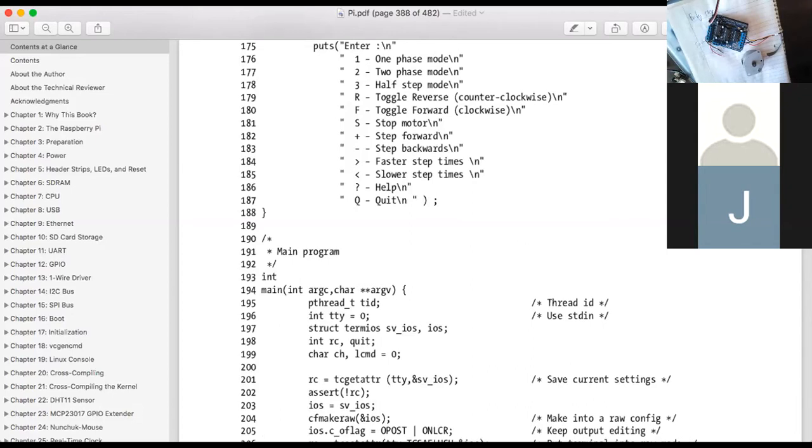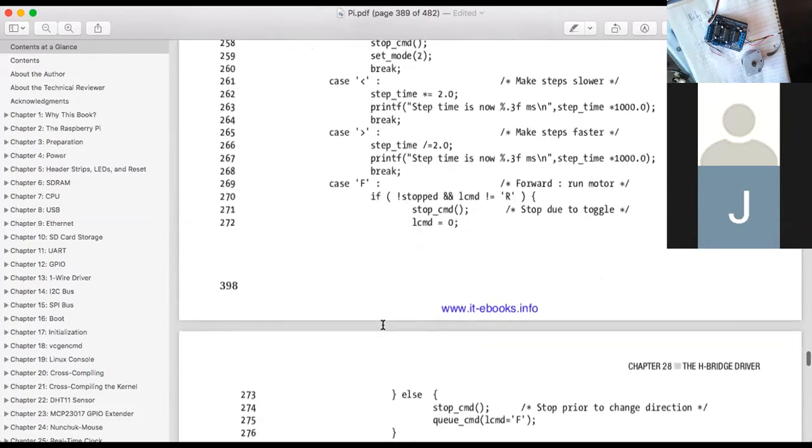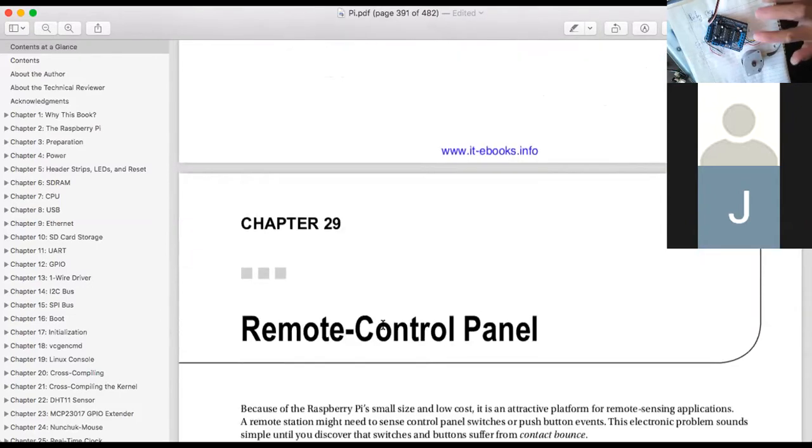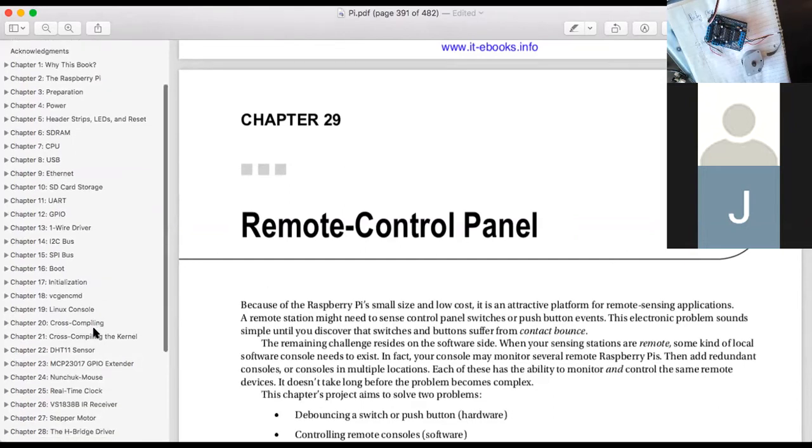What does that mean? That means one Arduino computer can control 16 of these cards. Each card can have 6 motors. 16 multiplied by 6 means how many? 96. So you can drive a maximum of 96 motors by one computer. If you're working on something really complicated and need 96 motors, then you can use the V2 version of this motor drive. So that's our first topic, 3 chapters.